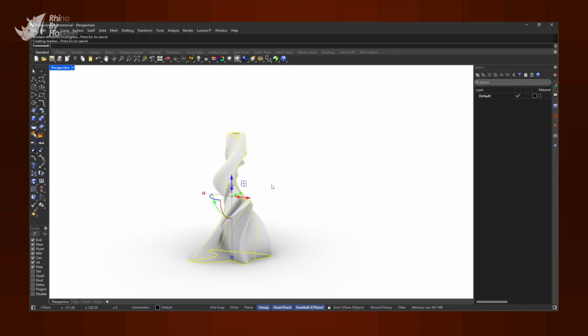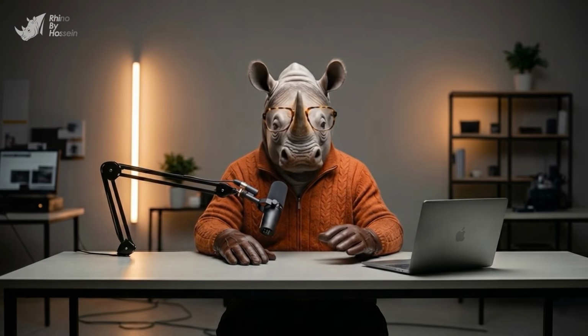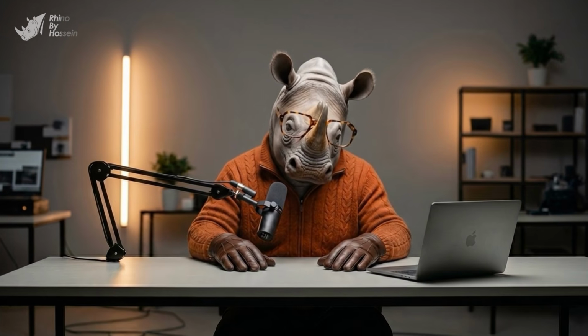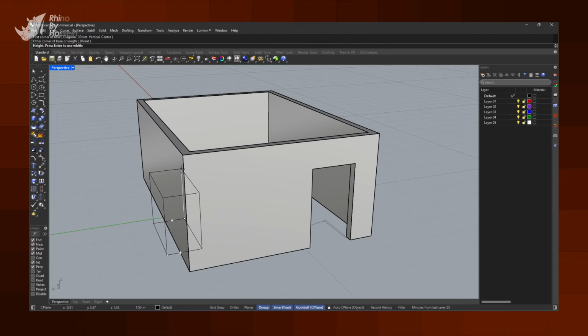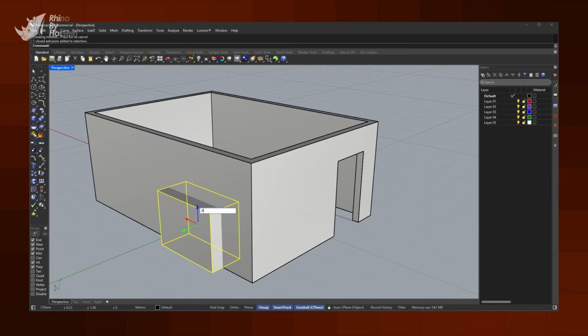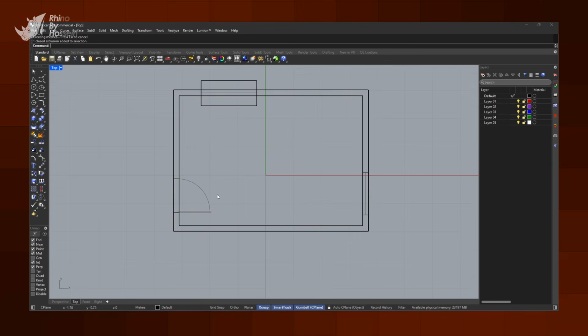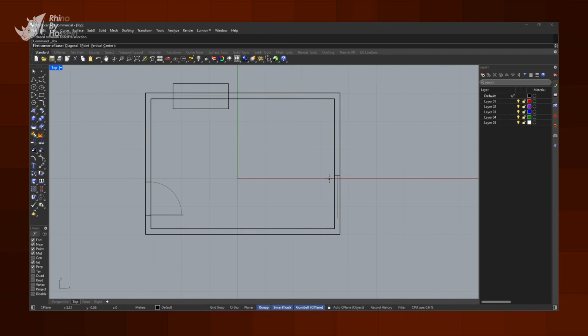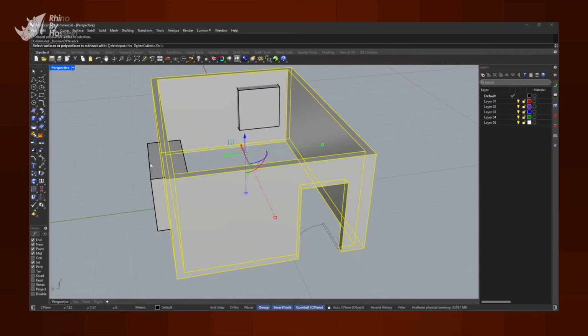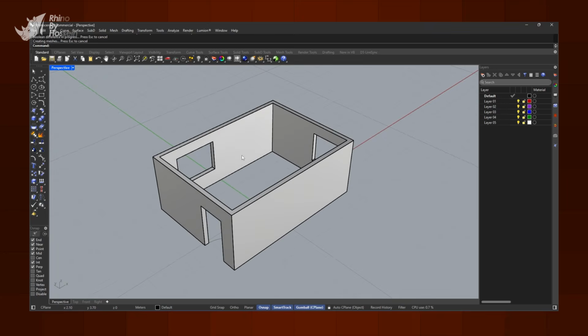This is actually one of those moments where Rhino is telling you something very important. Your geometry is not clean or complete. The problem is that most people ignore this signal. The solution is to always do a quick check before running any Boolean. Make sure all objects are properly joined, check for any naked edges or open boundaries, and clean up the geometry if needed. When these conditions are satisfied, Boolean operations almost always work smoothly. In other words, Boolean isn't broken, it just expects your model to be ready and well prepared.